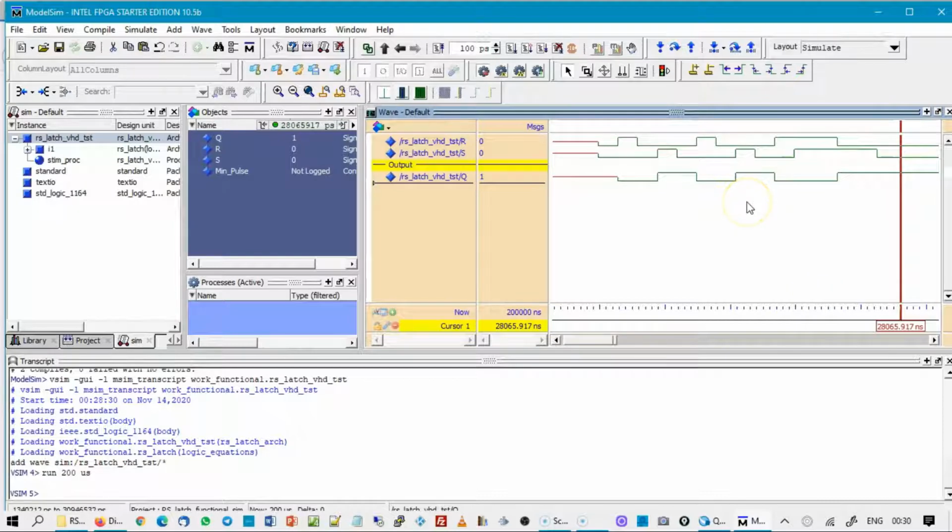So that picture demonstrates that functionally the circuit that we have invented works very well. It can be used in some applications, not very many, but in some applications, for example, a circuit like this connected to push buttons and switches may help you to get rid of switch bounces, which are a big problem in digital systems.